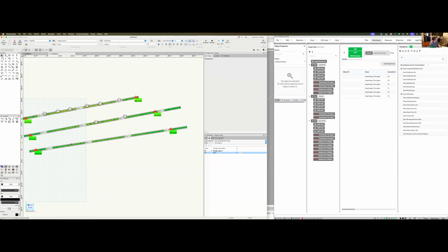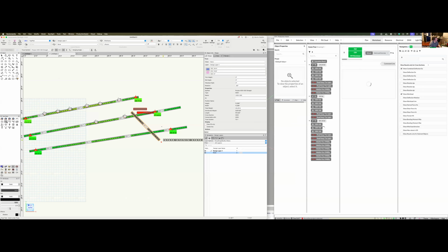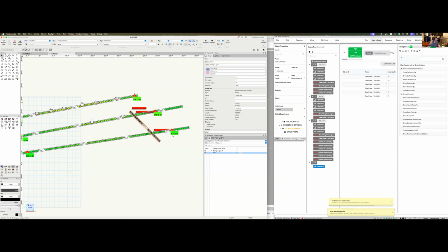Stacking trusses is an essential part of designing complex hanging systems, and Production Assist streamlines this process for you. Begin by inserting your base truss, which forms the foundation of your system. When you add a second truss at the right height, Production Assist automatically reads its geometry and connection points. Otherwise, you can use the stacking tool.